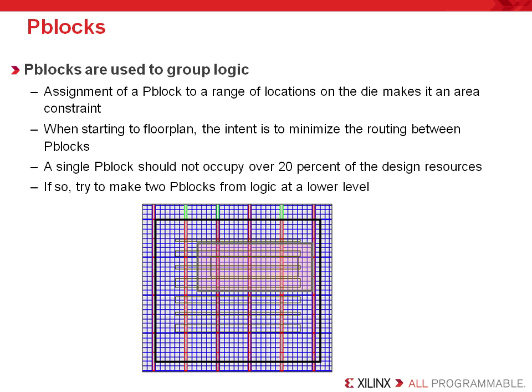The process of floor planning begins by dividing some or all of the logic in the design into groups and constraining that logic. The PlanAhead software provides the ability to hierarchically divide the design into smaller and more manageable physical blocks or Pblocks. These Pblocks can include logic modules and primitive logic from anywhere in the logic hierarchy.